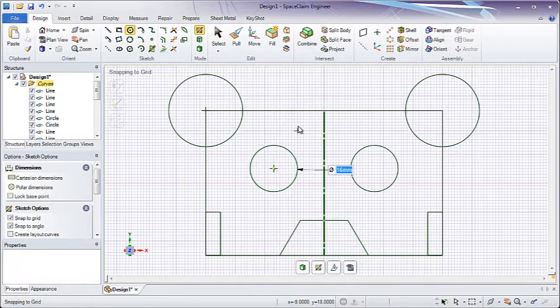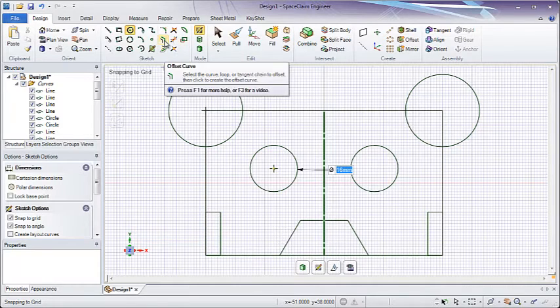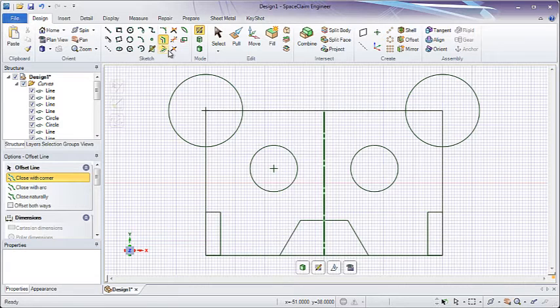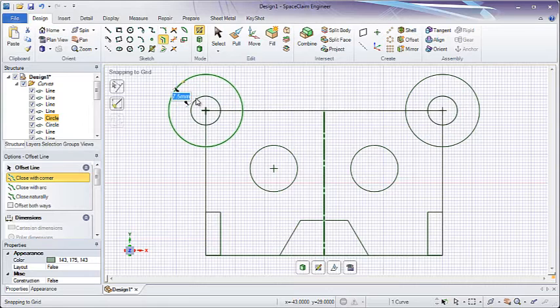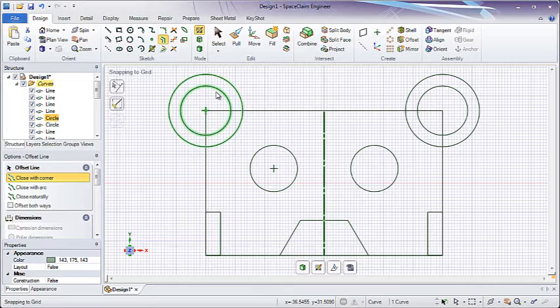Now, I've made most of the sketch that I want there. The last thing for me to do is to modify this. Remember, the tools on the left will create new things in your sketch, and the tools on the right will modify your sketches. For example, let's say we want to offset some of these curves. I'll click on our Offset button and choose this circle. Remember, because the mirror line is still on, if I offset this line, it's offset on the other side as well. I'm going to type in 4 millimeters to create that offset.